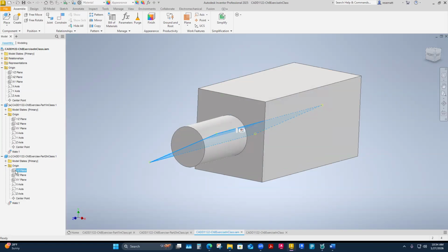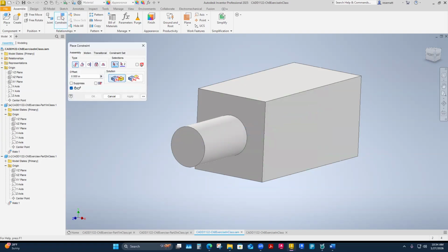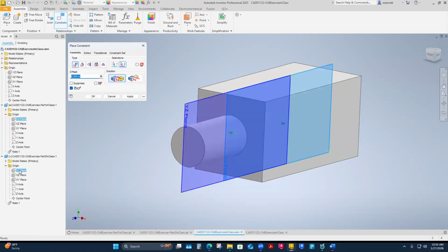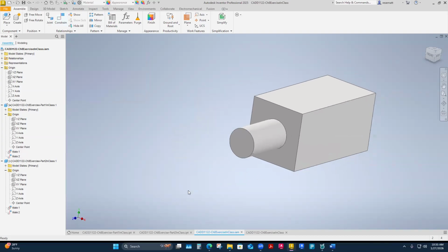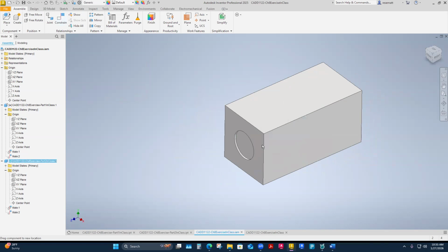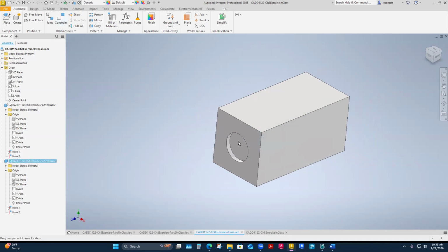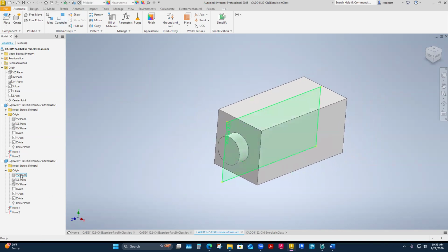They were built off each other, so technically their YZ planes should align. And so I think I'm going to do a constraint to align those two planes. Constraint. I'm going to say, I want this YZ plane to be the same as this YZ. And I'm just going to say, okay. They just share those planes. It still allows this thing to pull in and out. But it doesn't allow me to turn that thing now because those planes are locked together now, which could be bad.